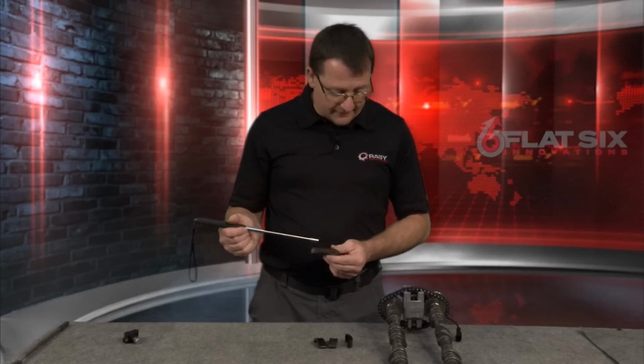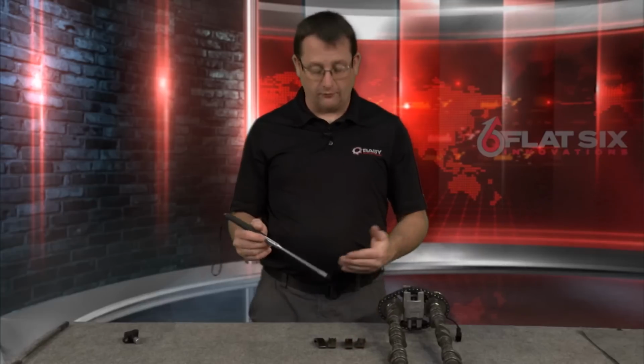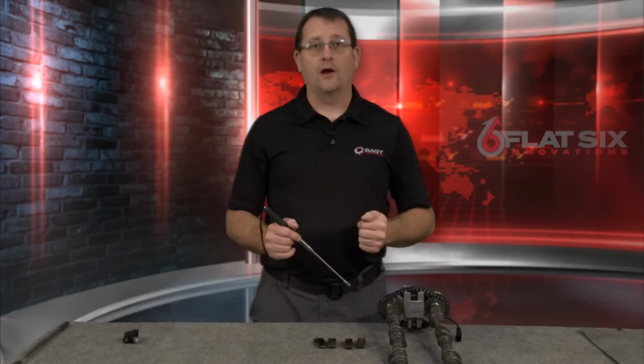So with these things being said, now we have to talk about how to avoid this wear from occurring, because we've already shown that these have wear. We've talked about the fact that the factory has made differences in the chain guide material, both for the main timing chain guides as well as these smaller ones for the 4th and 5th chains.